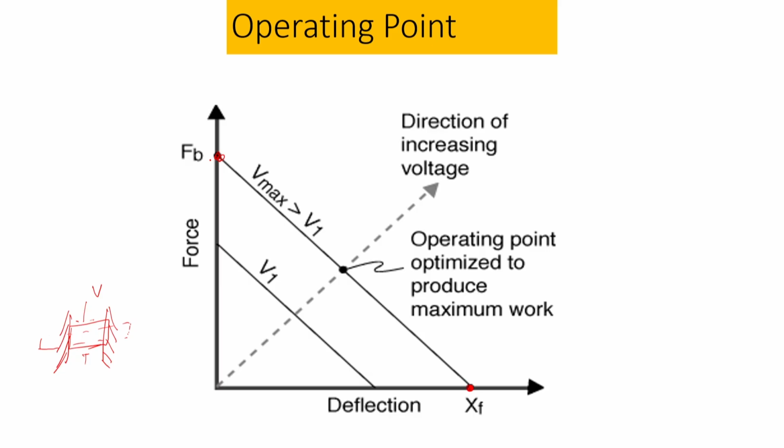Now, in reality, all piezoelectric material is in between this displacement and the blocking force, somewhere here, some amount of force, some amount of strain, and we always have to design where this operating point will be. That is part of the design activity.